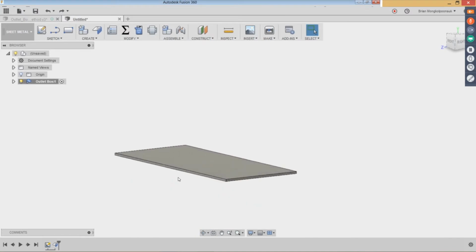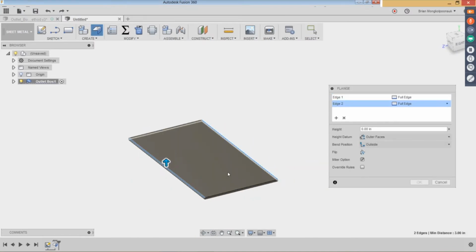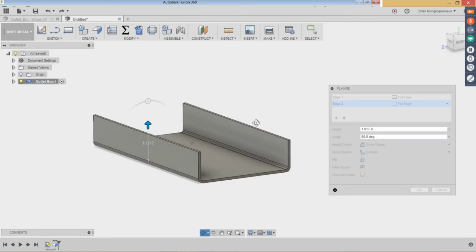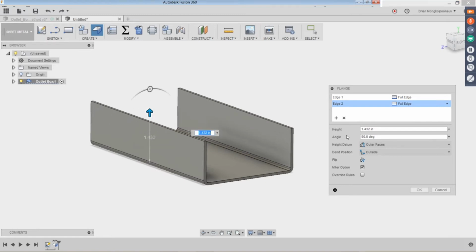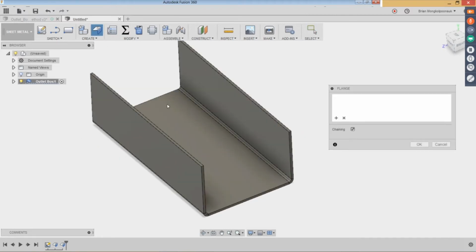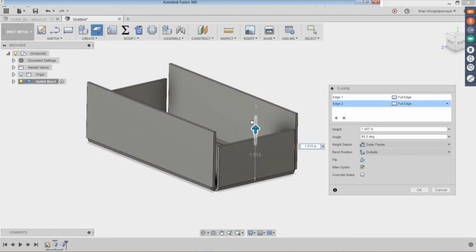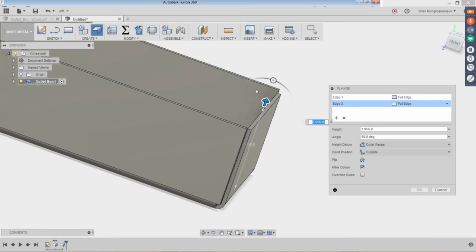All right, so let's go ahead and create that box that you saw earlier, the outlet box. However, instead of a welding approach, we're going to do another approach that doesn't require us to weld it. I'll go ahead and set this height to 2. And then I'll select these other 2 faces. And notice how they're on a different level than the original flange that I created.